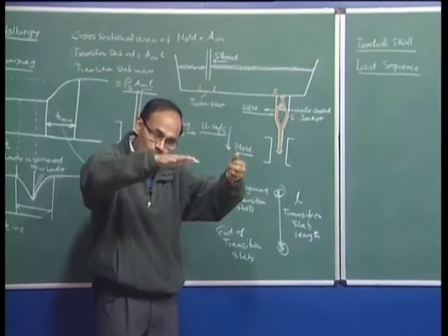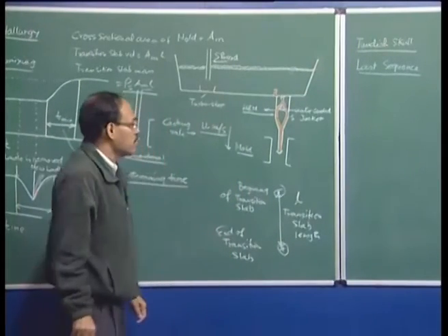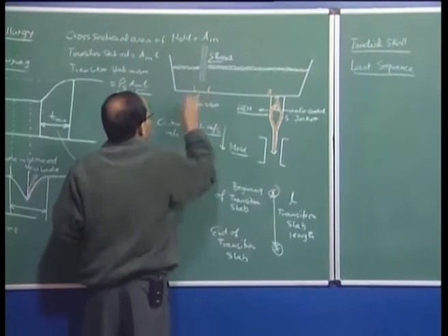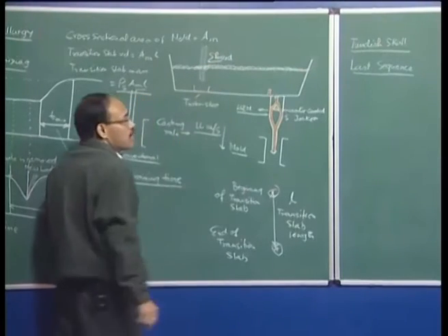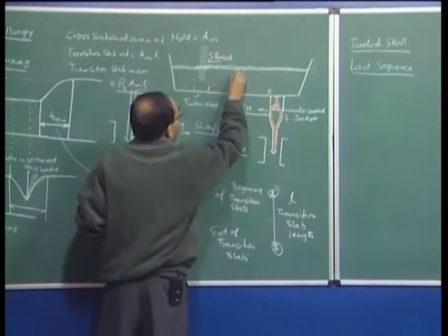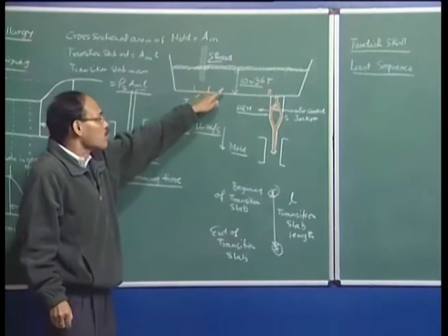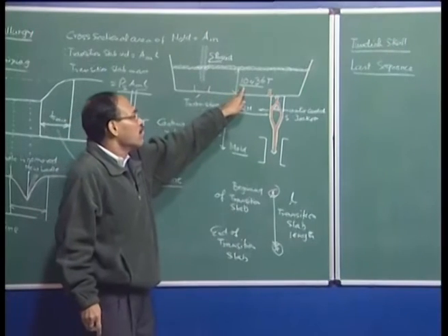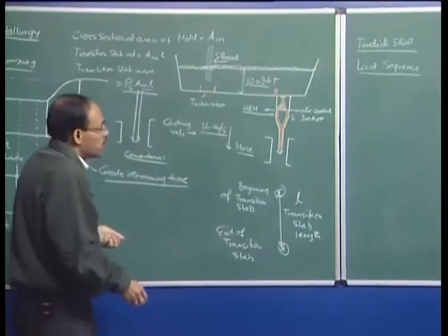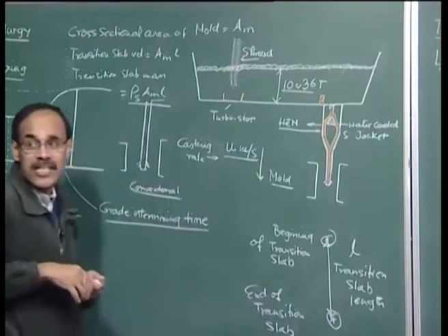So, the material in the ladle is going to be exhausted, and as it is exhausted, nothing comes into the tundish, and as a result the bath depth in the tundish goes down. So, at the moment this stops coming from the ladle, nothing comes in. Now, this is the instant at which the material does not flow from the ladle. We have about 10 to 28, maybe 10 to 30 tons, I have seen so much of material. This is the mass of steel in a tundish. So, this could be in a say bloom casting tundish, and this could be in a thin slab or a huge slab casting tundish. They can contain about 36 tons of material. So, the moment molten steel from the ladle is stopped, we have about 36 tons of steel remaining.